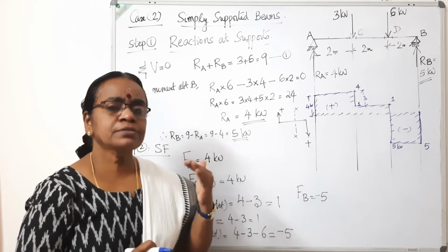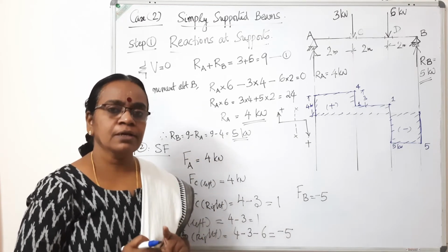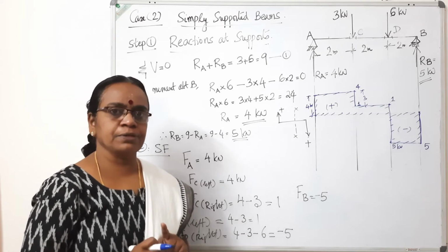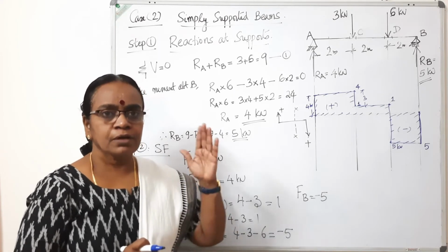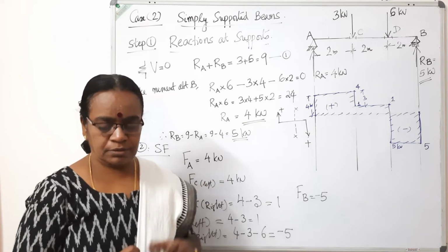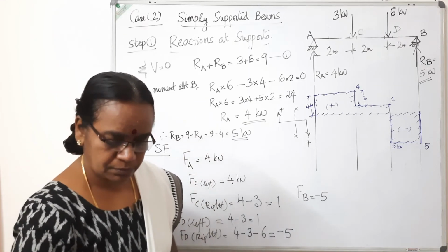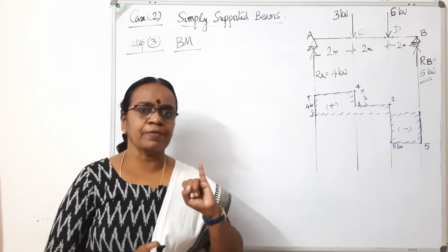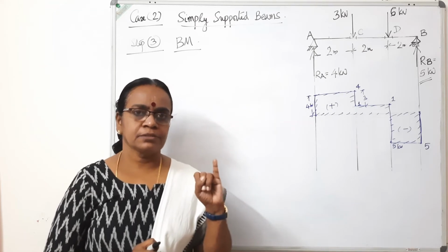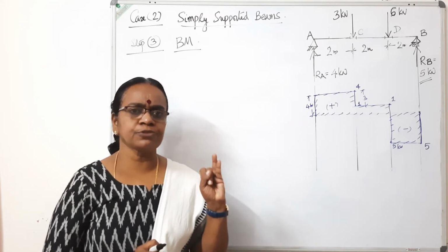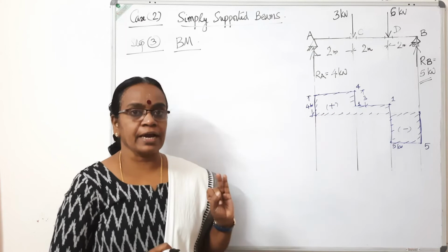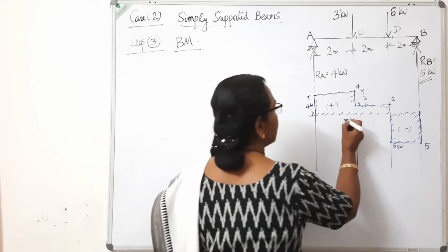Okay. Next, we have to pass on to the calculation of bending moment. Bending moment is also nothing but load into distance. Let us see that now. So, first step, we have calculated the support reactions. The second step, we have calculated the shear force and then drawn the shear force diagram. So here we have to write shear force diagram.